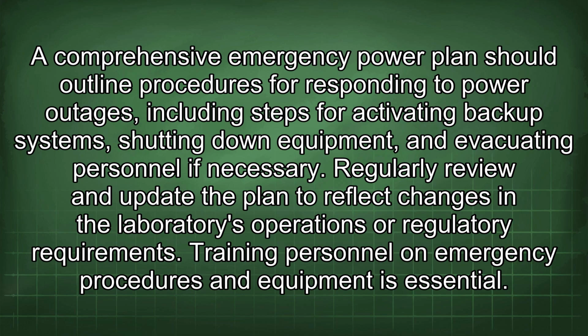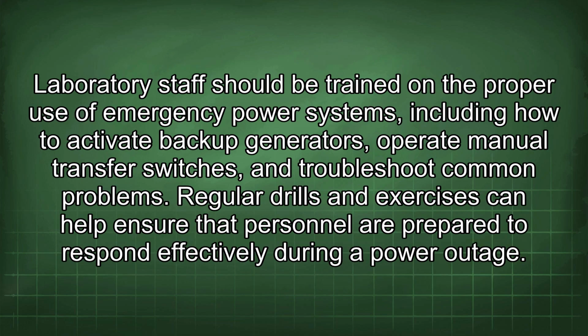Training personnel on emergency procedures and equipment is essential. Laboratory staff should be trained on the proper use of emergency power systems, including how to activate backup generators, operate manual transfer switches, and troubleshoot common problems. Regular drills and exercises can help ensure that personnel are prepared to respond effectively during a power outage.